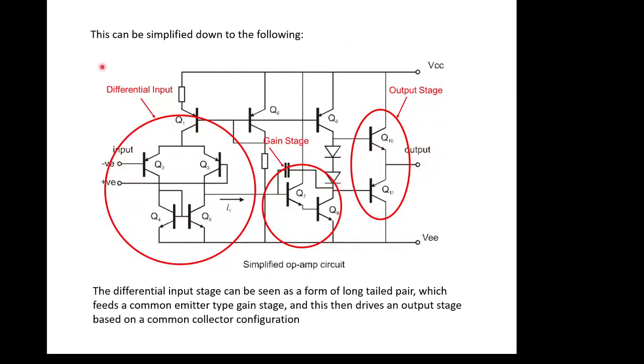And the overall gain of this whole system is around about 200,000, which is close enough to infinity to be really useful. More modern ones have much higher gain, but 200,000 is enough. One of the interesting things is this capacitor in here, which allows it to become stable under nearly all conditions. Because it becomes a short circuit at high frequencies, it actually gives us a feedback path that becomes a short circuit at high frequencies. So the gain is lost because it effectively shorts these transistors out.